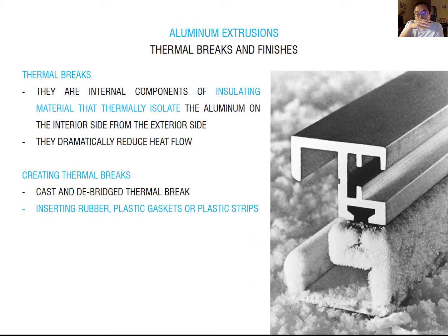So now, a very important topic. What about the thermal break window? You remember the aluminum window frame is a very good conductivity material. It means it is easy to transfer heat energy. It means through this aluminum frame, you lose heat energy from the inside. For this reason, you have to consider breaking the thermal transfer from inside to outside or outside to inside. So they design a low conductivity material between outside and inside.